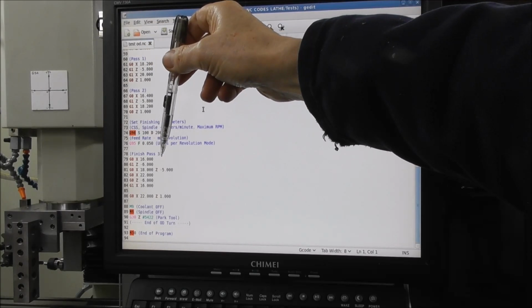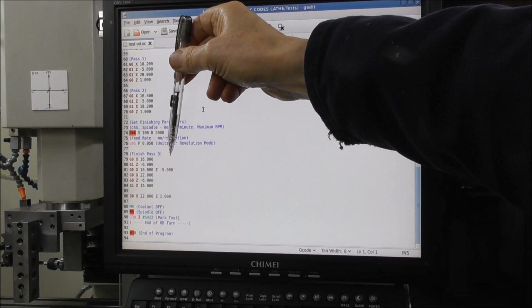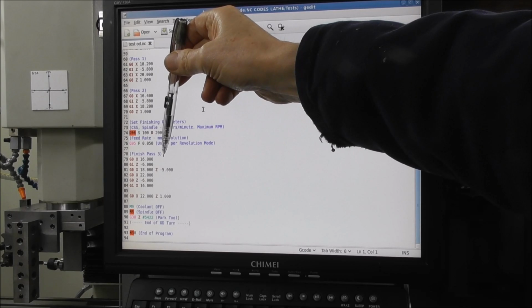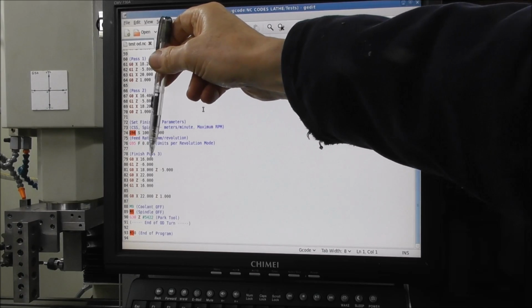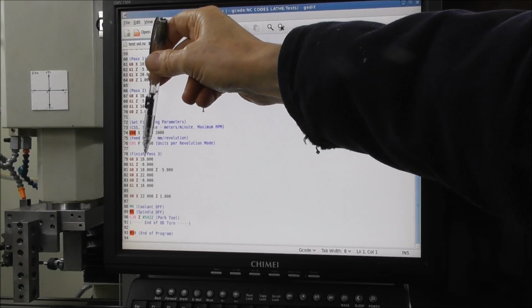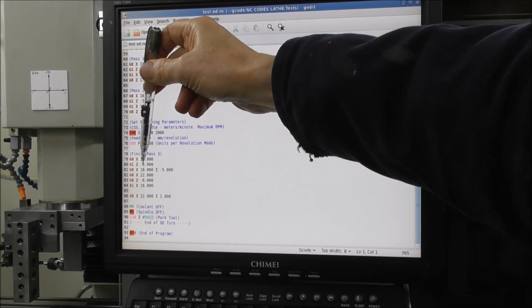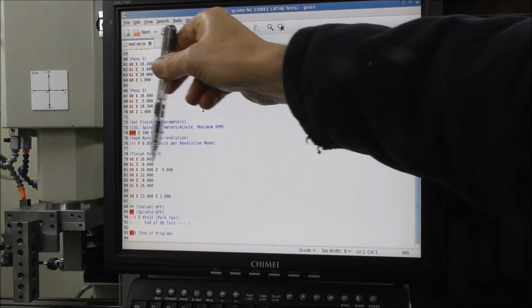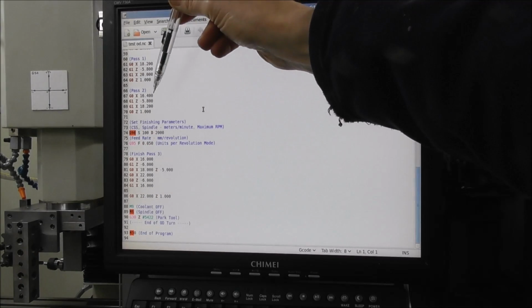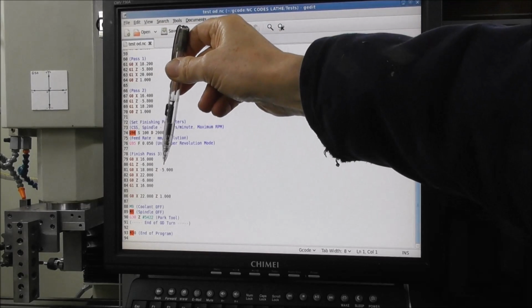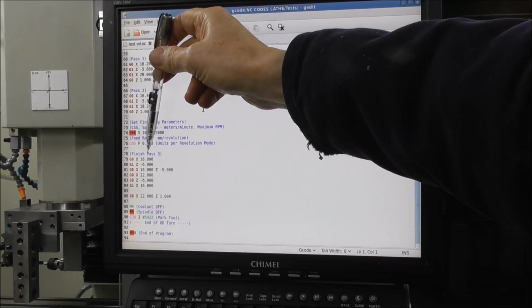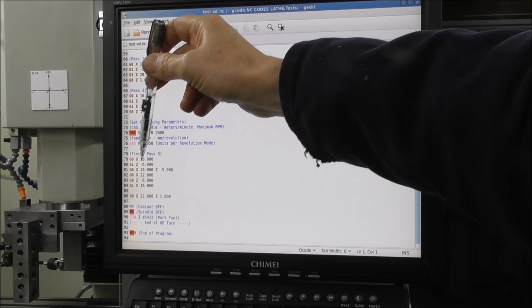And the finish pass, where we should be coming into the 5.8 again, it's going to a cut of 16 millimeters, that's the 0.2 cut, and it's going all the way to 6 millimeters. That's slamming into full depth. If that was more than just 2 or 3 passes, that could be a real major crunch up. Then it's coming back out.